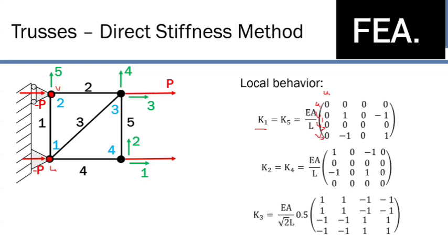Yeah, I'm sorry, guys. So now when it comes to V1, that's going to be this degree of freedom for the roller, which is unrestricted there. And based on the displacement in the other one, we can get one. So in its own, we will get one. And if the other one moves, obviously we're going to get a reaction in that one, so we're going to get a negative term here, right? U2 in that two direction, it's still unrestricted, so it's zero all across, and then V2, we're going to get that one. That makes sense to everybody?